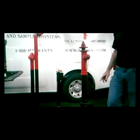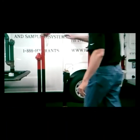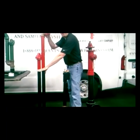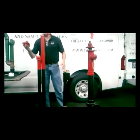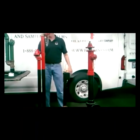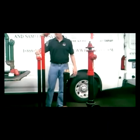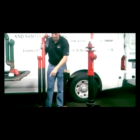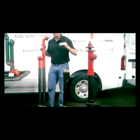The 77 is the other hydrant that's probably our second most popular one. And this is this one here. Again, where I bury the hydrant in the ground, right at the black line here. So this is above grade, this is below grade. It has a locking collar. We can do a locking on the number 2 as well, if you want to have a lock. This one has a locking cap. Curb stop operating nut. Okay. 2.5-inch NST outlet. Again, on these, we can do a 2-inch inlet, either a straight or a side inlet.